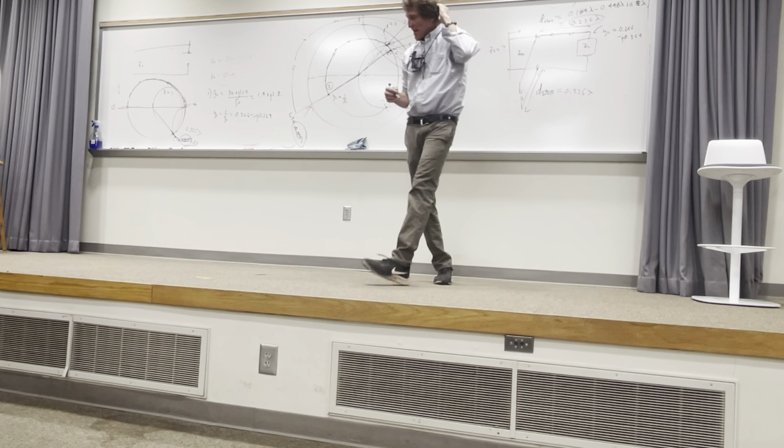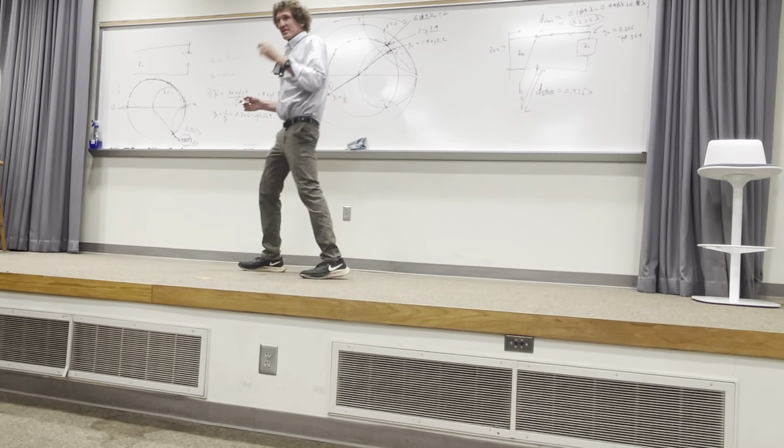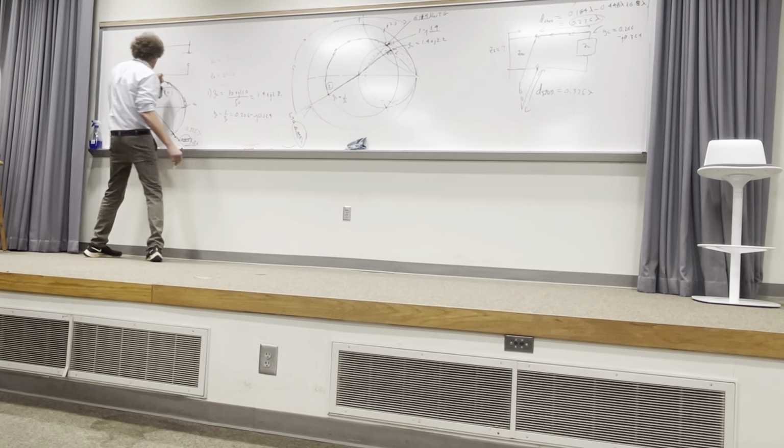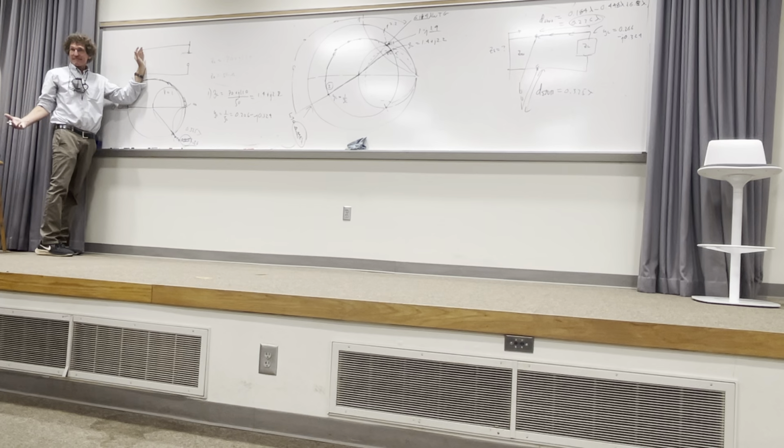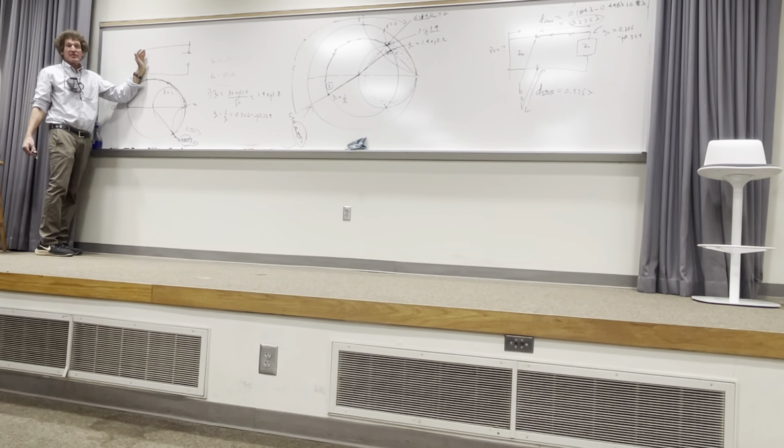By the way, tell me, what's the reflection coefficient on this line with an open circuit? Is it 1 or 100%? It's 1. It's either plus or minus 1 on any stub. It's never going to be 0.5. It's always either minus or plus 1. What's the standing wave ratio?